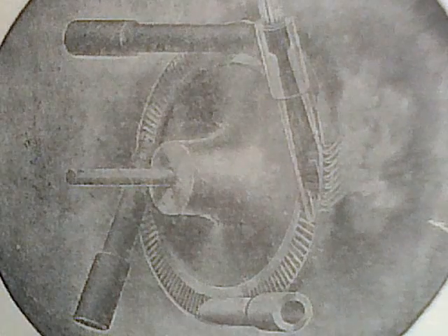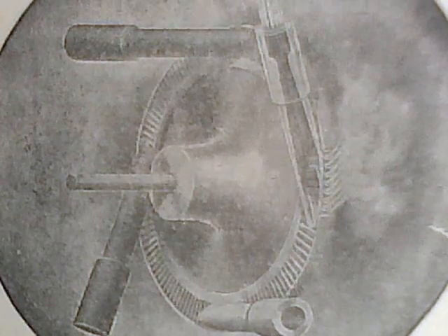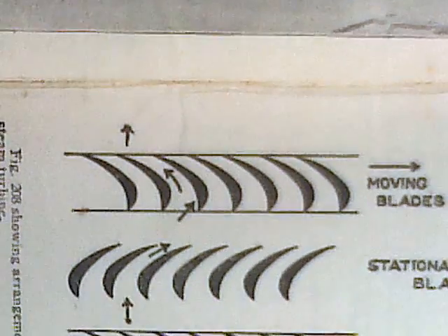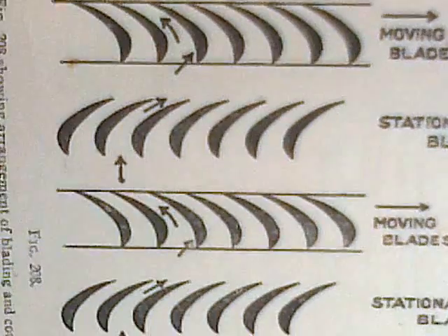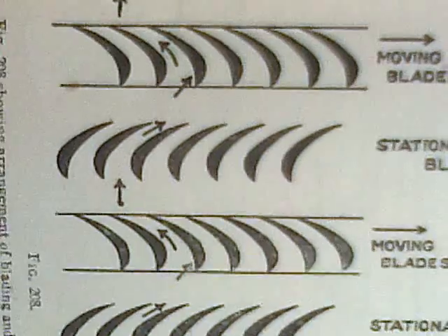Therefore, they got rid of all that reciprocating machinery and they moved to blowing steam on aerofoils on a flywheel. And they didn't just stop at one single row of blades. And as the steam expanded, the space it expanded into got bigger and bigger and bigger. Until by about 1885, when this book was published, steam turbines were 95% efficient at getting the energy out of the steam and into the shaft by using multiple rows of stators and rotors to squeeze all of the energy out of the steam.